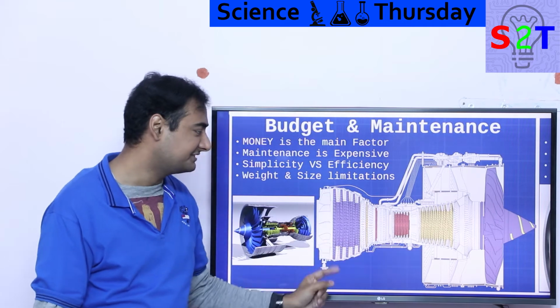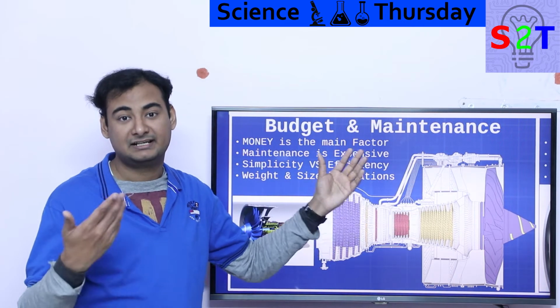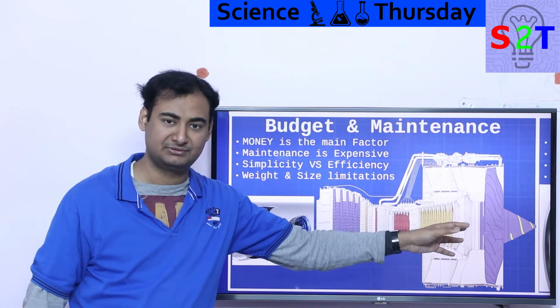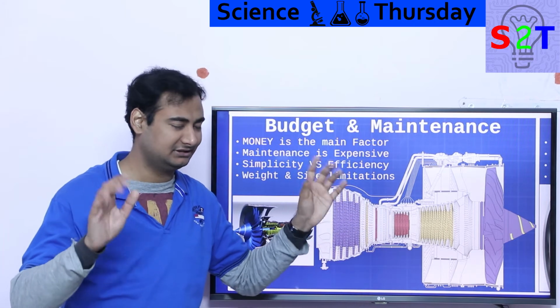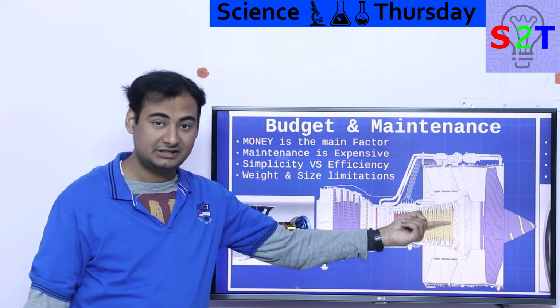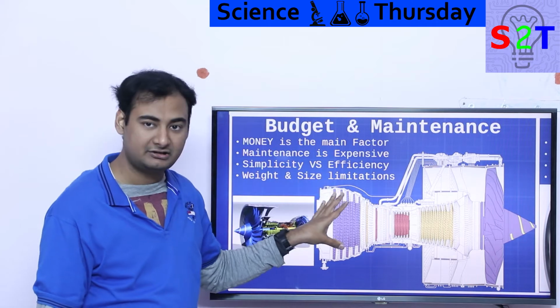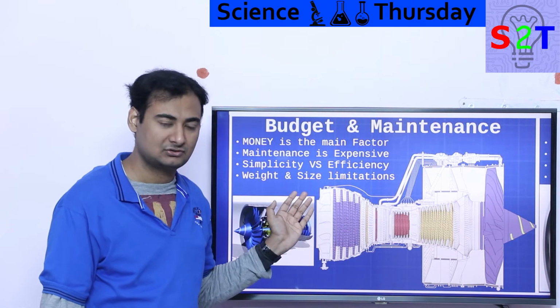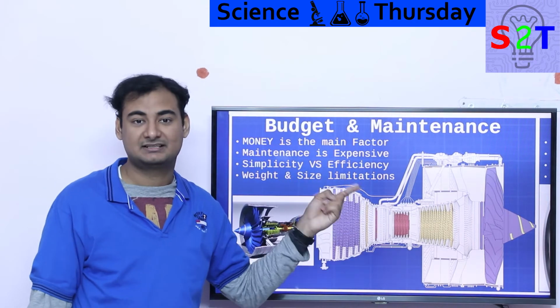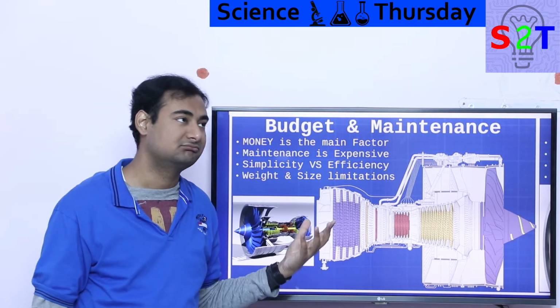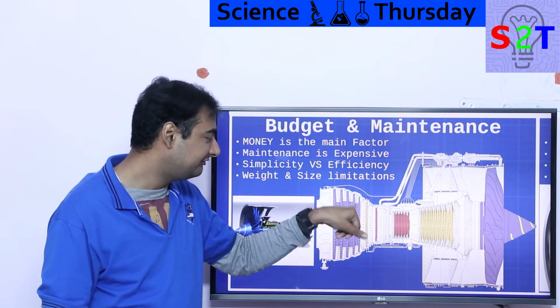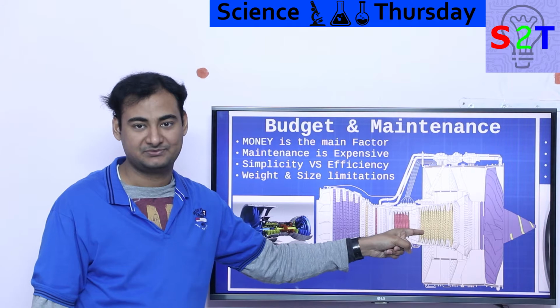If you have noticed the color differences, it has one fan. Fan likes to run at low RPM, so let's say 3000 RPM. Fan is like, okay, I get this, 3000, I'm cool. Now, to rotate this at 3000, you have a different turbine section. Okay, normal, everything normal so far. However, the compressor stage is going to stall at 3000, so it needs, let's say, 8000. So there is a different turbine to drive that 8000 RPM section.